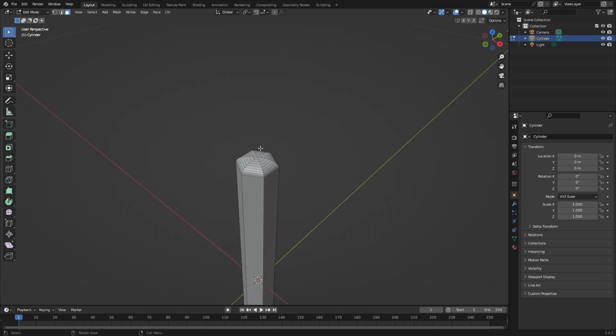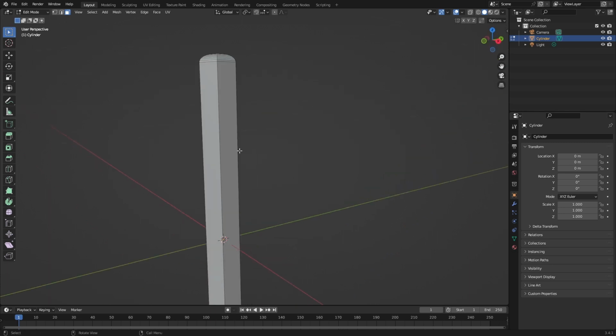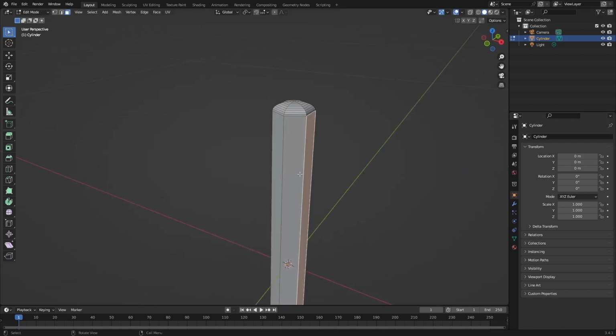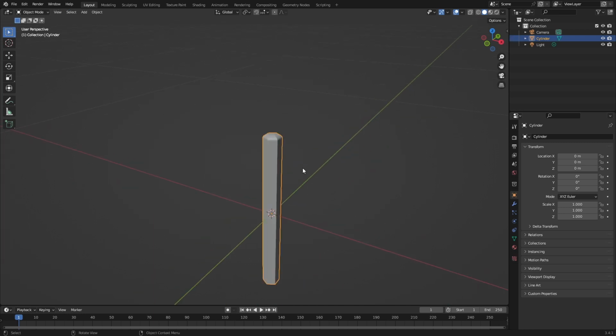And obviously remember to scale it down, you press S. And if you want to scale something along a certain axis, you'll press S and then Z, or S and X, or S and Y. And then you can even put in the amount you want it to scale by. So if I want to turn this entire pencil, I can press Tab to go out of edit mode so I can rotate the entire pencil.